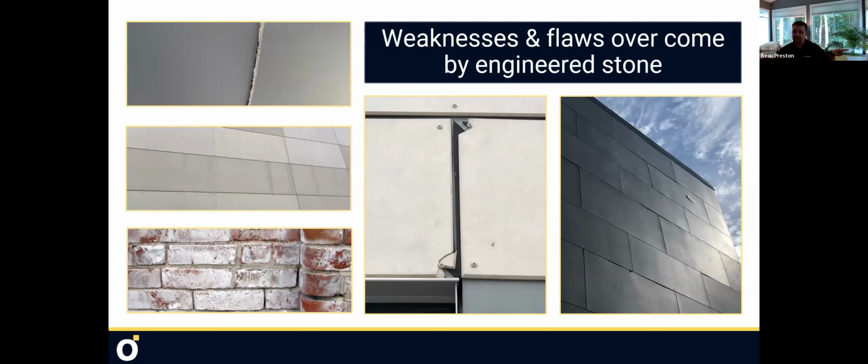Okay, the one in the middle, that is a high density fiber cement installed as if it was an HPL. HPLs can be installed with screws that are 1 inch from the edge of each panel. Those are obviously only 1 inch from each panel, and high density fiber cements need fasteners that are 2 inches from the vertical and 3 inches from the horizontal. And what do you have there? If you don't do that, you have 100% joint or a corner failure. You will have a panel that grows and will pop a corner so that it fits in the space that you gave it to fit in.